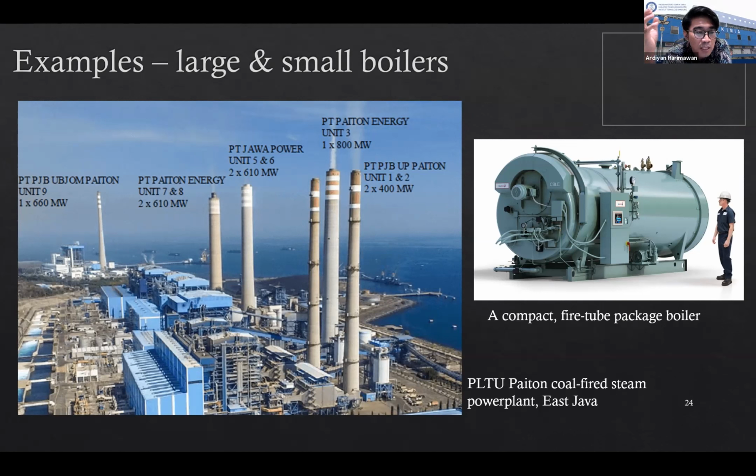It cannot be captured, because previously, if we have fly ash, you can capture it with the cyclone or the electrostatic precipitator. But if the ash is melting down, it carries to the next step, or it can stick to the heating surface, and then it can make problems there. It can create corrosion, it can create ruptures, etc. So that's the problem with ash fusion.